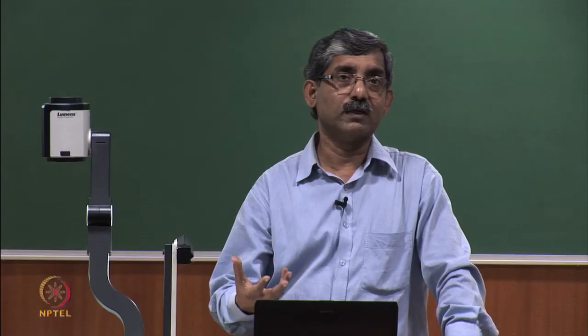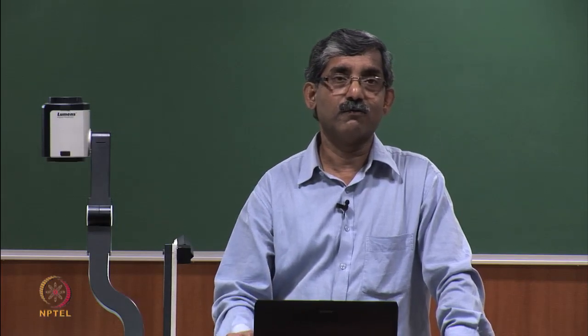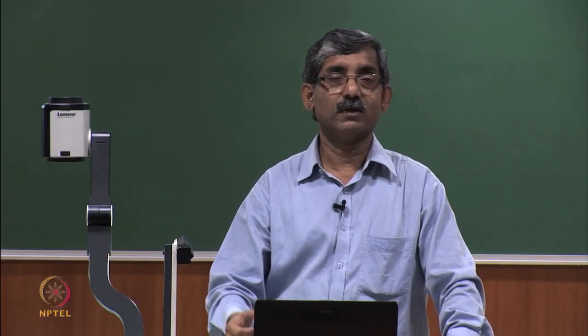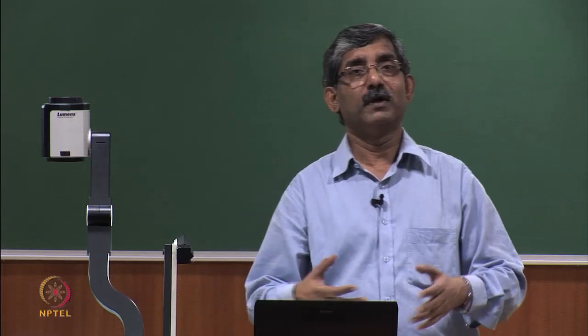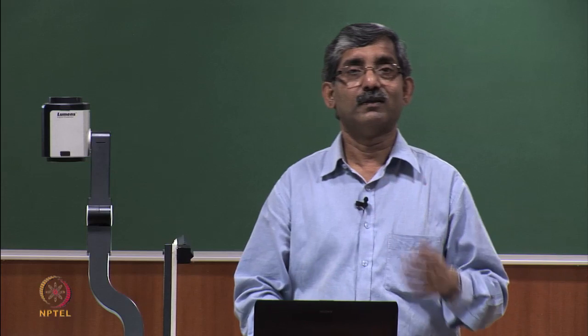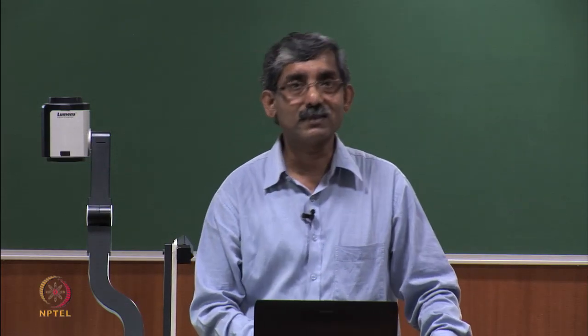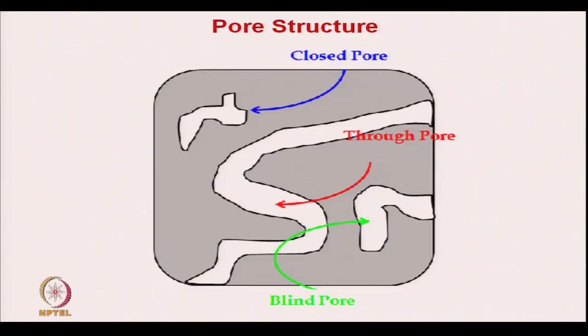Solidity and porosity are very important terms as far as filtration is concerned, because if the material is porous, then it will allow the air to pass through easily with less pressure drop.